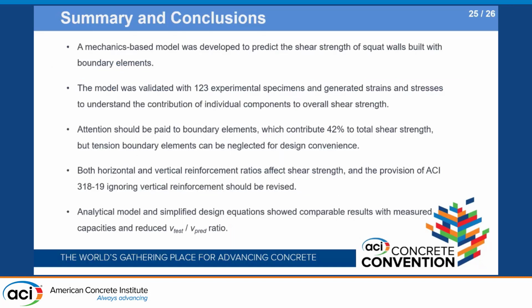So, conclusion. A mechanics-based model was developed to predict the shear strength of SCOD walls built with boundary elements. The model was validated and generated strains and stresses to understand the contribution of individual components to overall shear strength of walls in nuclear power plants. Boundary elements contribute greater than 40% of total shear strength, but the tension boundary element contribution was relatively small and can be neglected for design purposes.